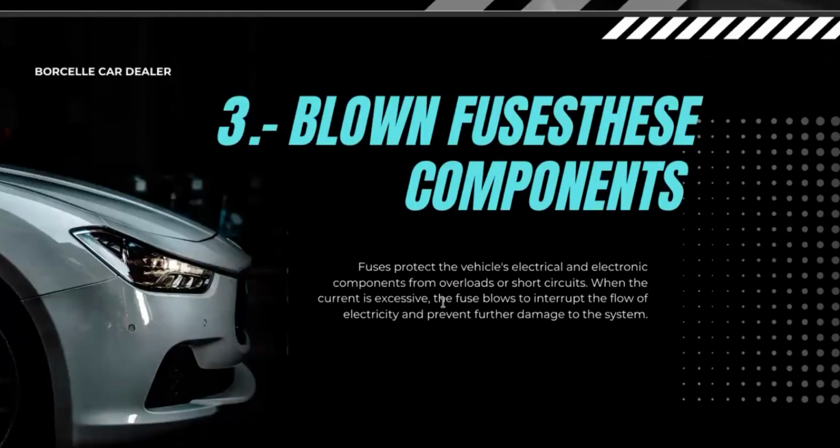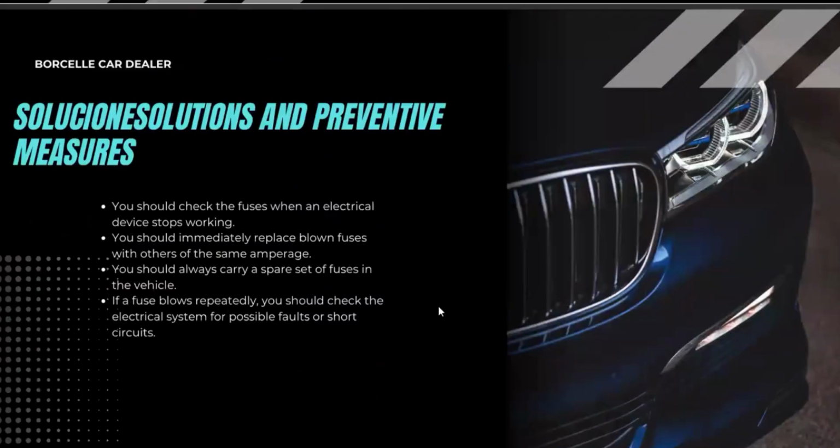3. Blown fuses. Fuses protect the vehicle's electrical and electronic components from overloads or short circuits. When the current is excessive, the fuse blows, interrupting the flow of electricity and preventing further damage to the system. Solution and preventive measures.